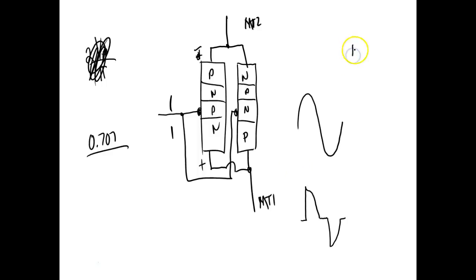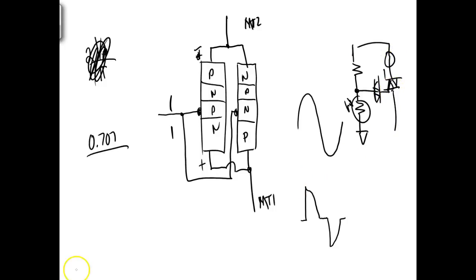All you'd have to do is come up and do this. So you have a resistor, and then you'll have a photo resistor, and then you just gate your triac. Then here we're going to look at a device called a diac, which is basically kind of like a zener. And then you would gate your triac over here. And then your light bulb would be up in here somewhere. Let me do a little better job drawing that.